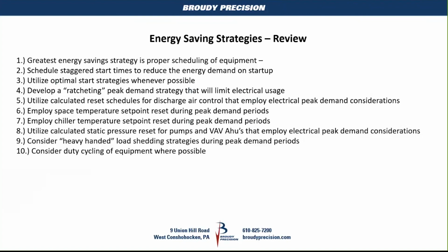The problem with proper scheduling is, if I have 15 air handlers and I turn them all off at 6 o'clock at night, at 6 o'clock the next morning when I turn them on, I probably don't want to turn them all on at the same time. Because when I do that, my kilowatts are flying through the roof, since I started up all of my equipment at the same time. So there are things that we can do to stagger our startup.